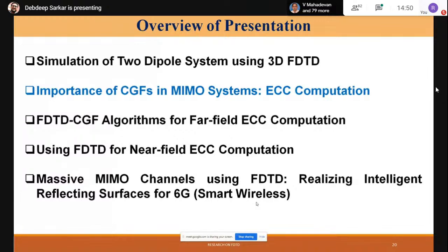And one very good thing about 3D-FDTD, or all the FDTD routines that I have so far discussed, is that they are explicit. So you really do not need to go for any matrix inversion. Since matrix inversion is out of your way, life becomes very simple, and since these are explicit equations you can parallelize. In fact, I already showed the parallelizing scheme using Matlab vectorization. But that is just a simple one inbuilt in Matlab; there are ways to even speed up the entire process.